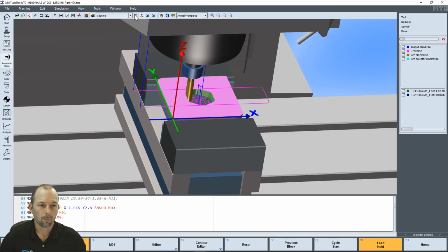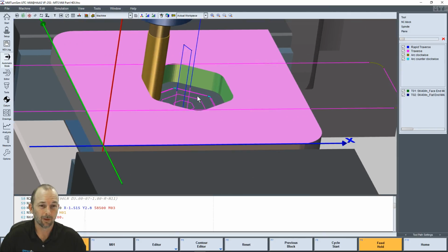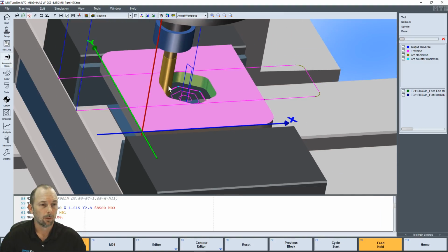The toolpath turns on the toolpath, and now we can see, similar to the BackPlot function that some visualization softwares have. And you notice when I click BackPlot, then I see my options for BackPlot. I can shut off tools. I can select or deselect whatever I want to, and we can also deselect any rapid movement, straight line movement, and arced movement as well, and only see the movement that we're looking for. We can also scan through our program and show the movement on each line of program. So if we're trying to isolate a certain piece of the program, this helps us to isolate a piece of the program.